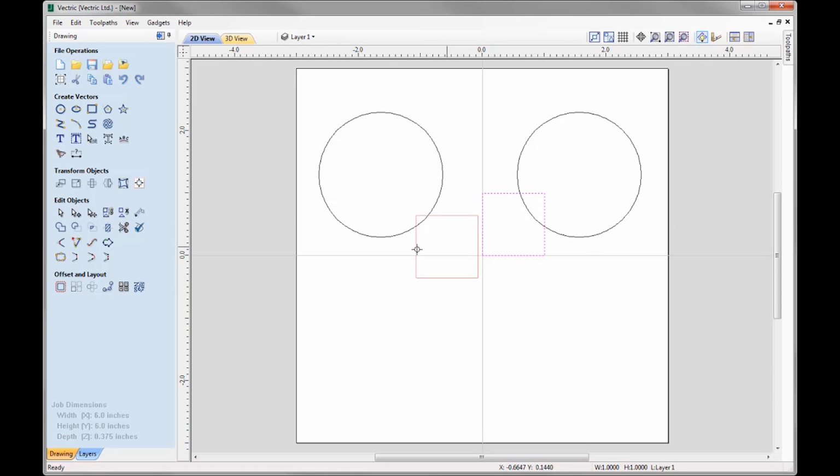So let's just take that square, I'm just going to move that over. I mentioned that we can also use the transform shortcut keys to rotate an object. So I'm going to take that handle and start rotating it and just type in 45, you can see that at the bottom, followed by enter, and it will rotate that for me by 45 degrees. So again, much quicker to do it this way than to have to go into the rotate objects form to then put in a number to rotate the object by. So let's just undo that.